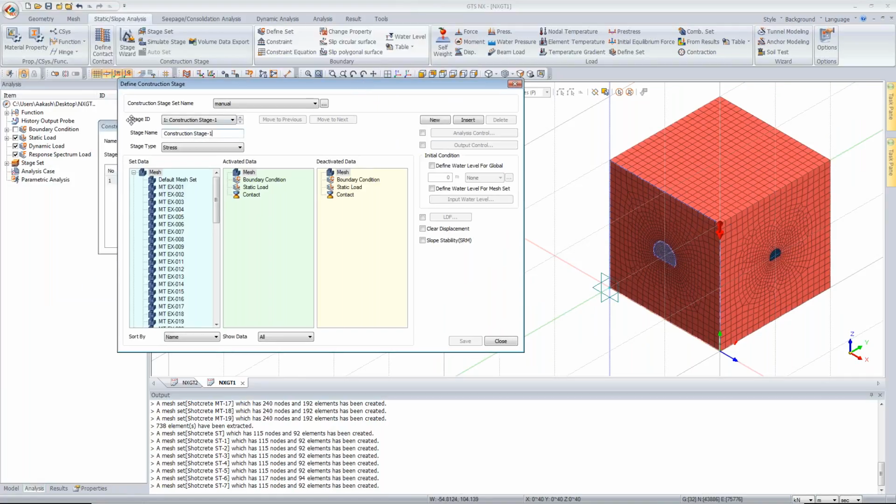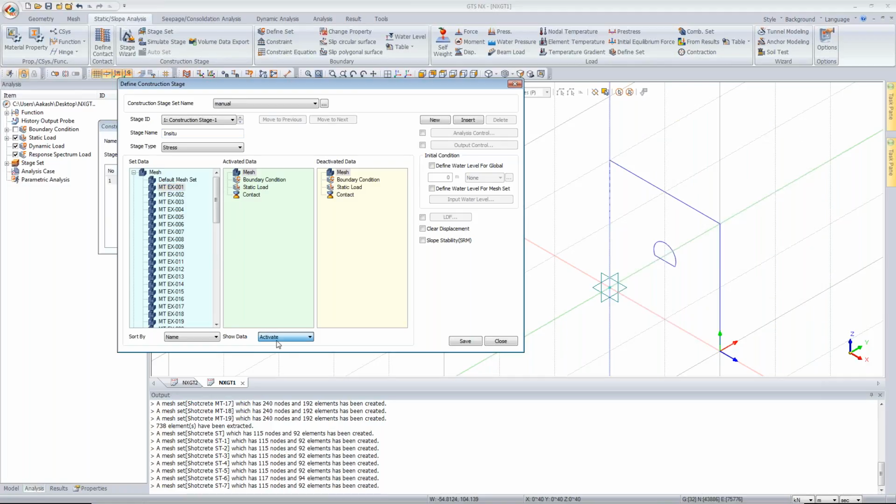As you know, for any geotechnical model, the first stage should always be in situ. Whatever is present exactly in the ground. All soil condition, basically no construction till now. So in situ, we have all the excavation soil. Now you can say activate. Whatever you activate goes into the analysis, and you can simultaneously see what you have activated.